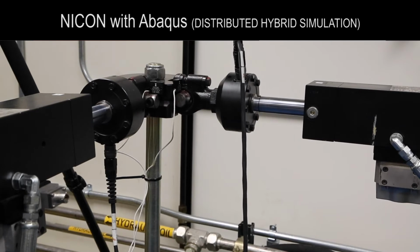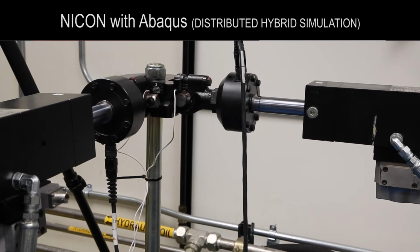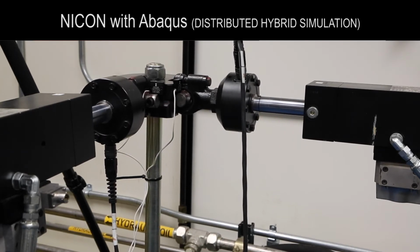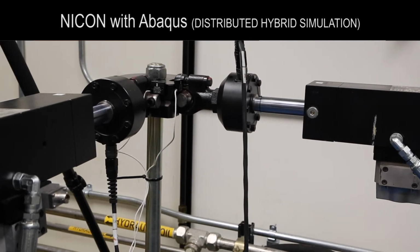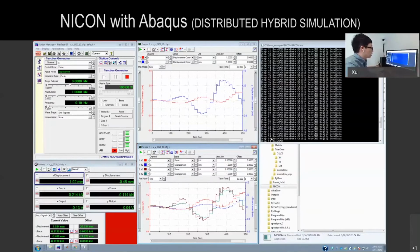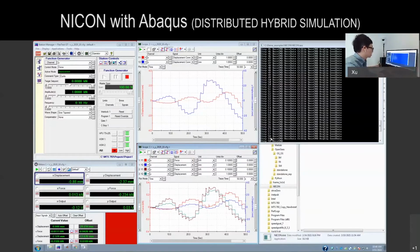Because Abaqus is using an implicit solver here, it takes 3 iterations for each time step. That's why you can see that every time step has 3 iterations, right? So it may take a longer time than the OpenSees model, because in the previous OpenSees model, we were using the alpha-weight schemes without any iterations for each time step analysis.